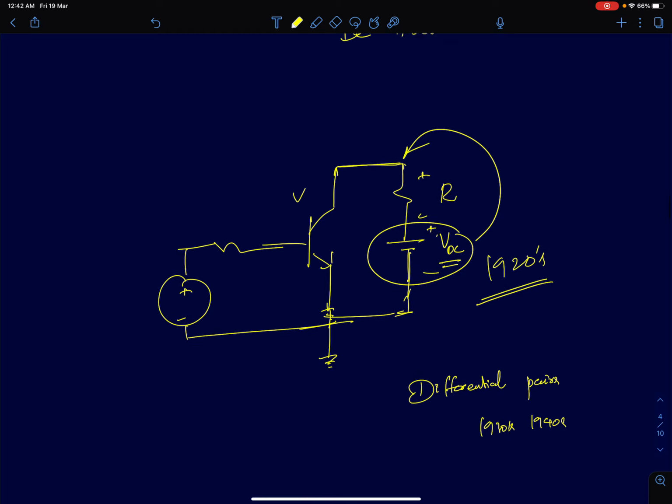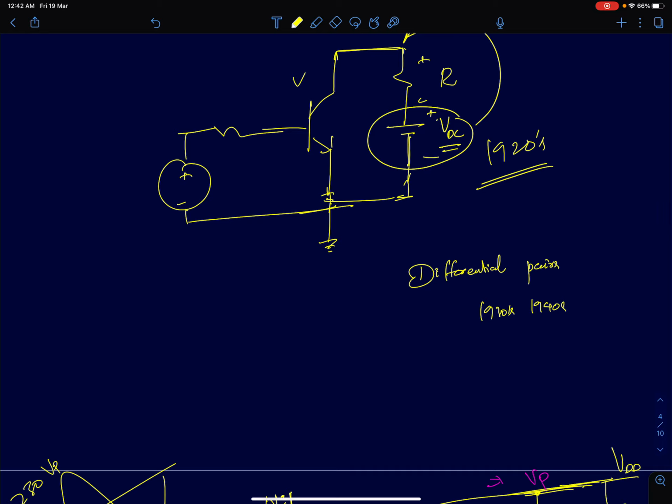So this again is a circuit from very basic electronics. We use what we call diode rectifiers. These are the circuits which can convert AC to DC. Of course, there are far more advanced and more interesting AC to DC converters now, but I'm talking about a very simple generic AC to DC converter, which is the diode rectifier. So a diode allows current to flow only in one direction.